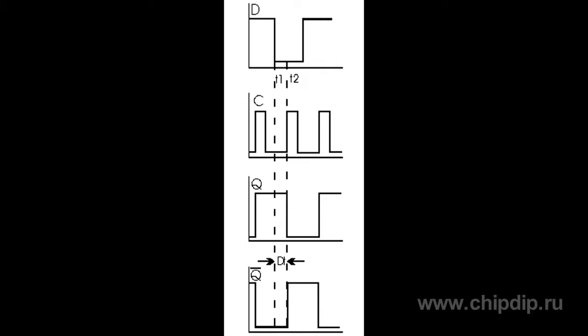C input is a pulse input. The pulse input is insensitive to the signal level. This input triggers at the moment of transition from one level to another. These inputs are referred to as triggering at the leading edge, i.e. in 0 to 1 transition, or triggering at the trailing edge, i.e. in 1 to 0 transition.